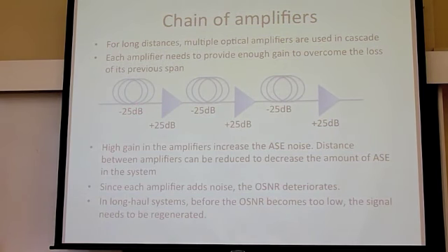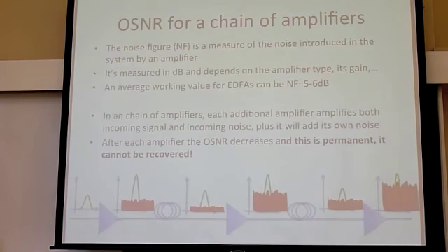And this is a huge advantage in terms of signal to noise ratio, for sure. And in any case, if the signal to noise ratio gets too bad, then there's nothing else you can do. You have to regenerate the signal. So stop the link, read the bits, and then create them again. So that's basically what happens in an optical amplifier.